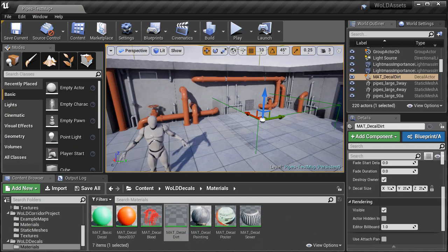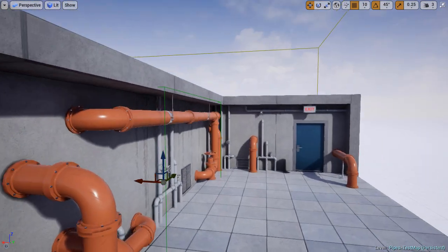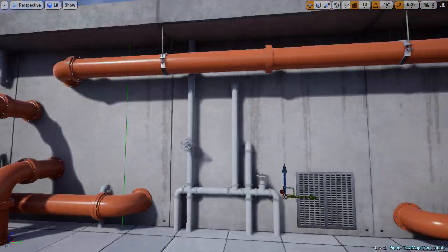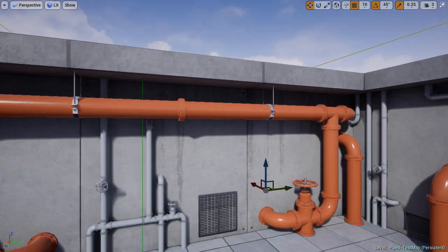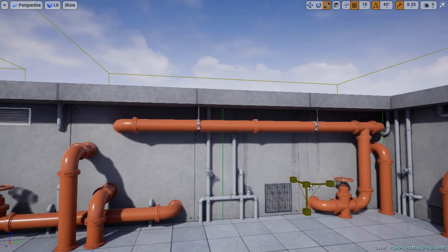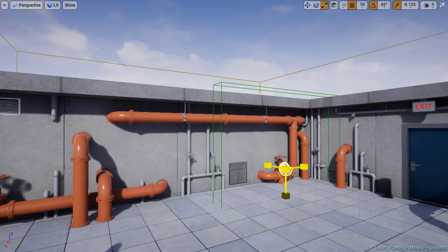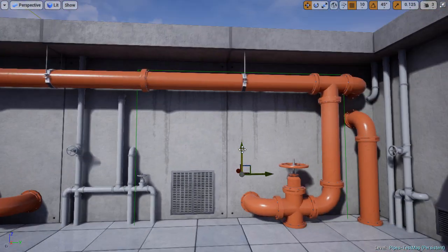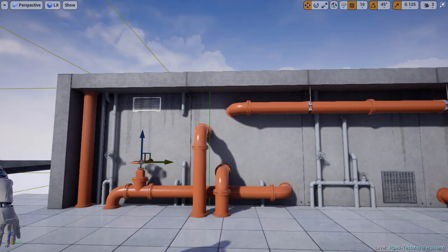So I'm going to drag this decal dirt into the map, then rotate it and project it on the wall. Position it right here. And then scale its influence, its depth, how far it's being projected. And you want to get that distance as low as you can because it will help you optimize that decal usage. Then I'm going to duplicate the decal and position it next to it. You can get a lot of reusability from the decal by duplicating, readjusting its position, and then scaling its size so it appears a bit different than the one next to it.